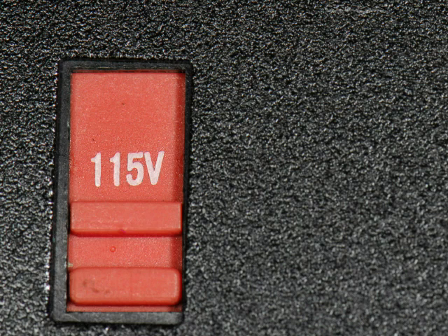I don't know why this is a big emphasis, because most people don't just haul their computers off somewhere else. Usually they'll take a laptop, and laptops normally have power supplies that auto switch, so you don't have to worry about it. Some of the power supplies that come in your computers will also now have auto switching, so you don't have to flip this switch. It'll just automatically detect how much voltage is on the outlet that it's plugged into and switch internally accordingly.